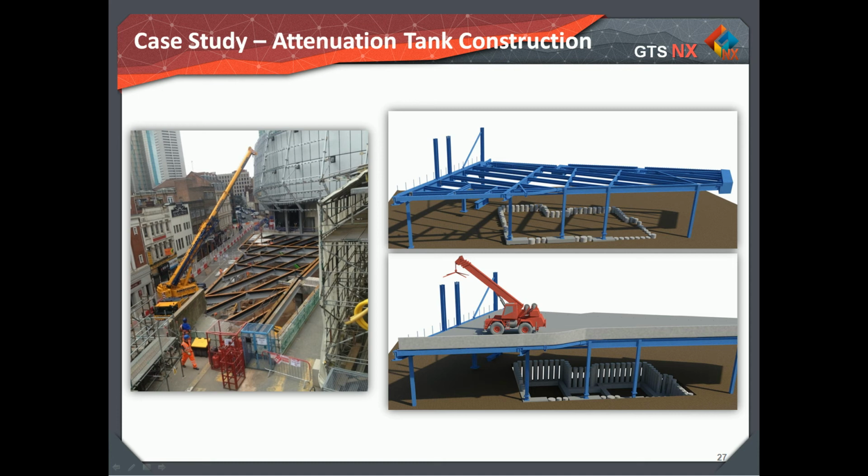However, in temporary conditions, that is during excavation to form the tank, the wall acts as a cantilever for which any excessive deflection would have affected the structural steelwork already installed and supported by a number of contiguous piles. The photo on the left shows the steelwork which had to be installed prior to any excavation. The ones on the right are obviously the 3D models of the steelworks and attenuation tank below.